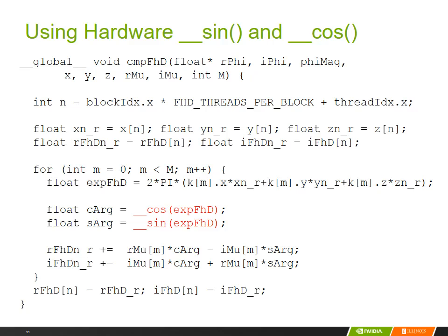As it turns out, the hardware function units actually provide sufficient accuracy because the MRI sample data are sampled with only a limited number of significant bits from the sensors, and so the limited accuracy of cosine and sine implementation actually preserves enough of the original data accuracy that we will not affect the final result, as we will see in one of the next slides.